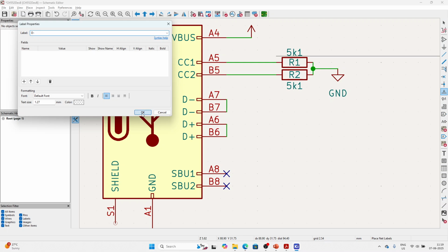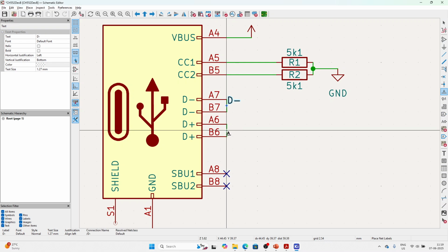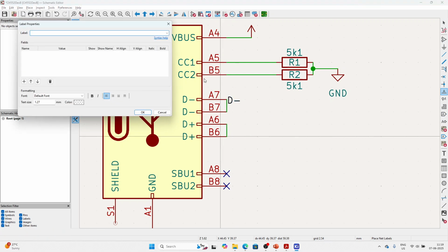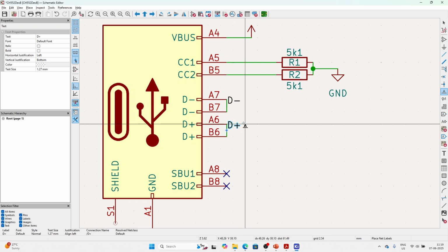One neat thing about KiCad, however you want to pronounce it, is that it comes with differential pair routing. That takes the majority of the headache away from the designer with respect to differential tracks. A differential track means tracks running simultaneously with each other, with equal distances between them so that they are impedance matched and do not interfere with each other's frequency and waves. That is called differential tracking.